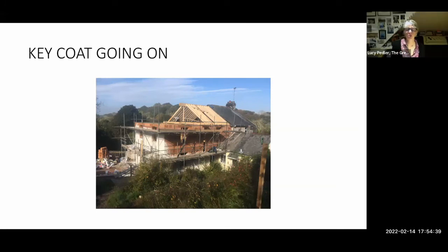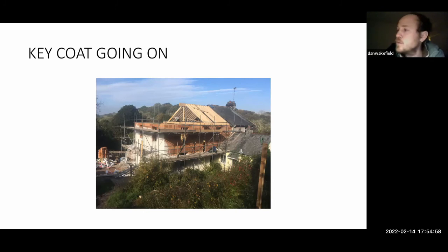Okay, I think some of Harry's question has been answered, but there's a reference to point loading, or strategic points where perhaps a lintel or a structural load rests onto them. Is there anything you have to think about in terms of beefing up that part of the wall? Well, we've done a few different things. Like I said, we did form a column at one point, but where there's a particular point load, the easiest way is to put in a couple of U blocks and form a little concrete lintel where that loading is going to be, and then it distributes it much more widely. So the blocks where you saw the joists sitting in the wall, that's what we've sat them onto, generally, if there's not a lintel there already.